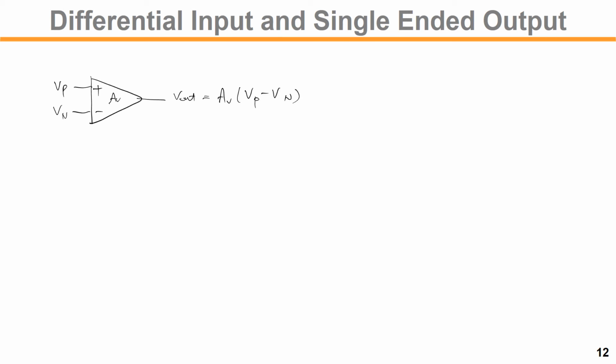So this kind of amplifier you can build. How? So first, for the input, you draw the differential pair, VP and VN. For the bottom, we have a transistor for current source, the bias. This is VB bias. And what about the load?